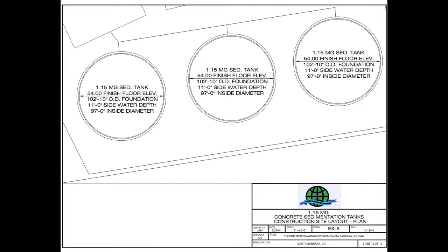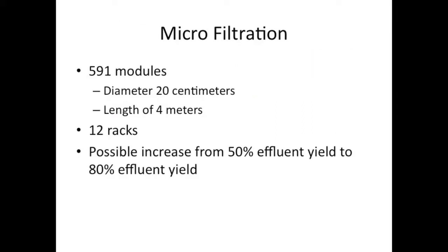Chemical agents such as alum and ferric chloride are added to the influent seawater in order to remove particles through coagulation and flocculation. This process is crucial for ensuring proper function of the filtration devices that follow the sedimentation tanks because it protects them from fouling and gives them a longer lifespan.